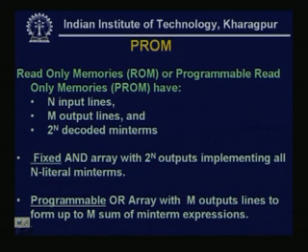Address means we give which memory element I want to get, and output is nothing but my memory content. So, here the specification is that there are n input lines, m output lines, and 2 to the power n decoded minterms.